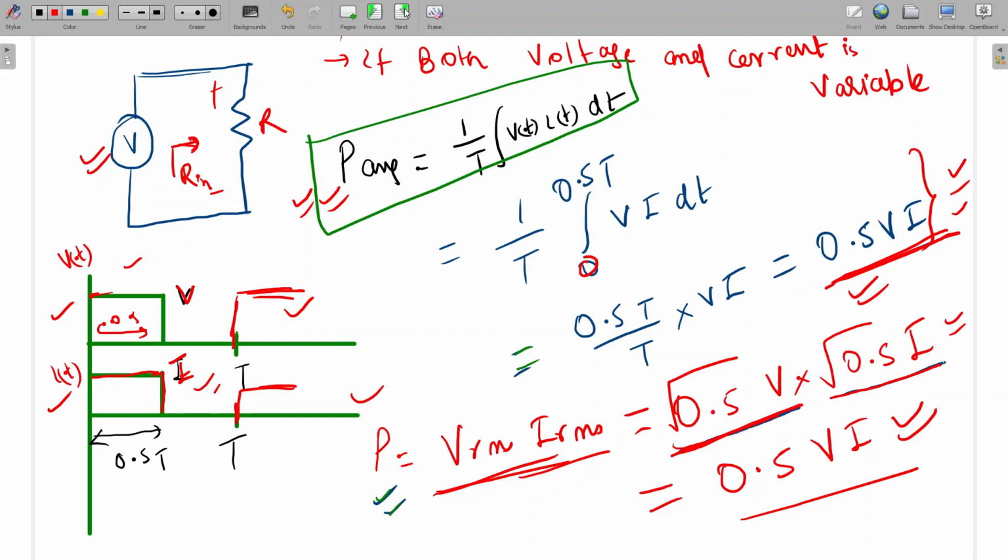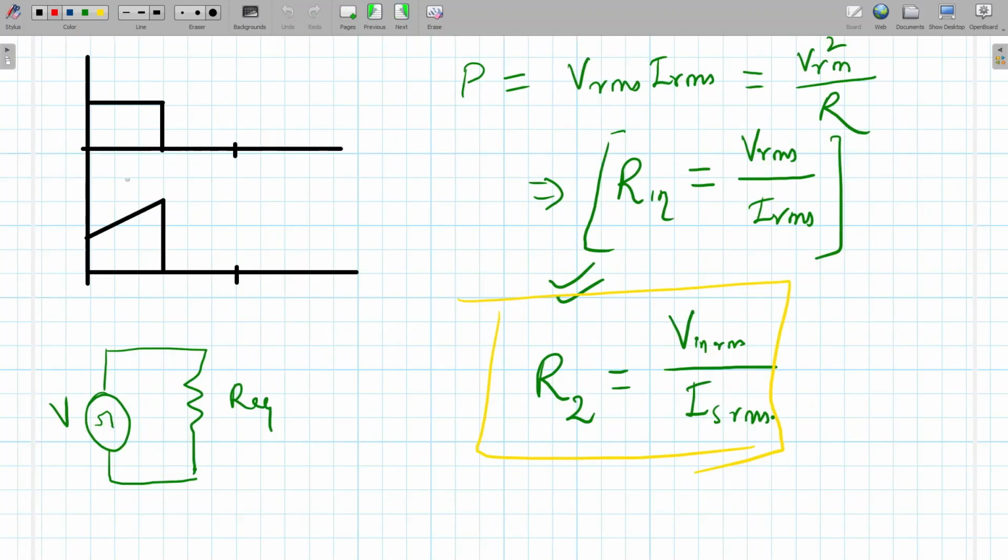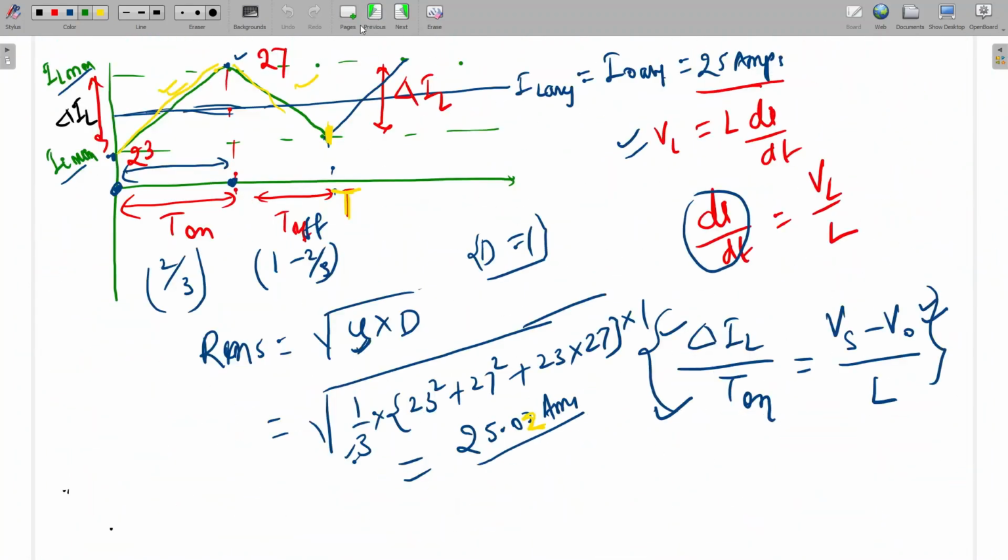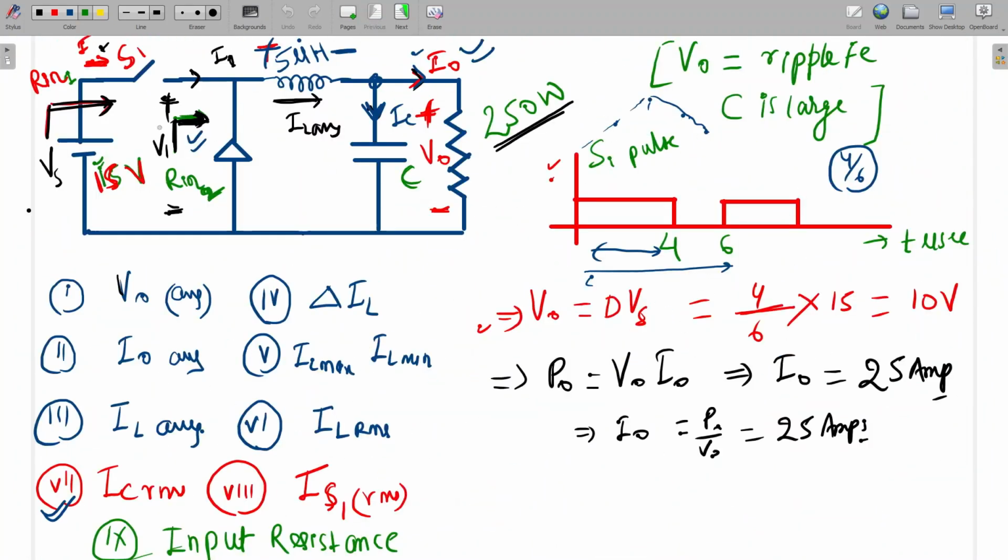One second. So here I have drawn the source current. What will be the voltage here? The voltage will not be constant, it will be a periodic voltage from here to here. This is V1 and this is I1. I1 will be present when the source conducts, for the duty interval, and in the next interval the diode will conduct. So the voltage here will be variable.